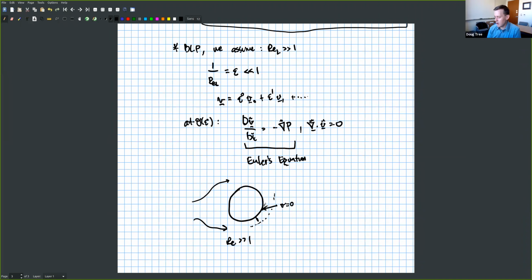So I see some staring. We could go through the math on a specific example, and we are going to in a minute. We could show that if we assume this Euler equation, we end up not being able to satisfy the boundary condition on the inner surface. This is like some of these boundary layer problems, which could be a good problem to do for your project. You could pick a boundary layer problem like a wire, where you have to solve both momentum and thermal boundary layers, and you could work this out.